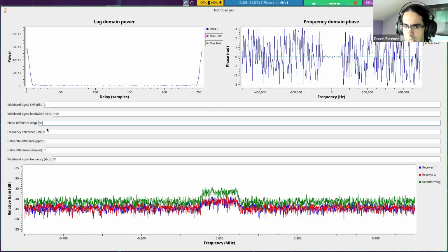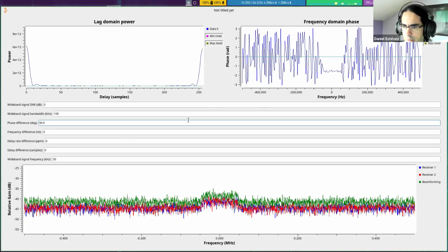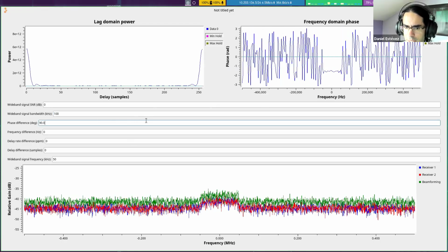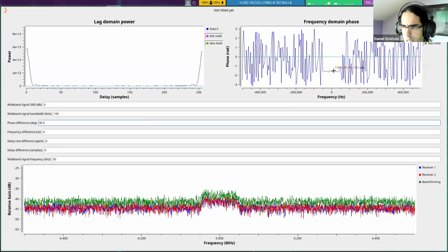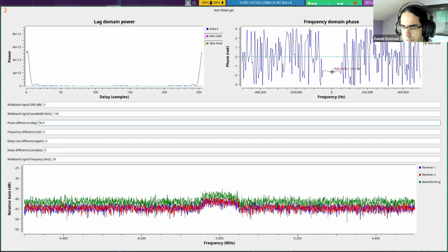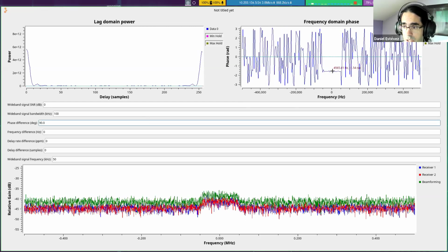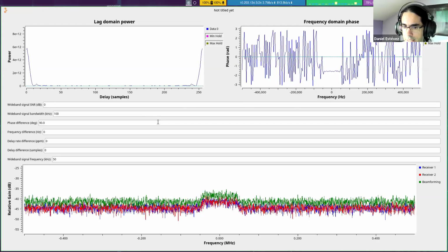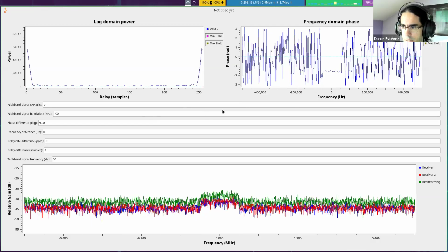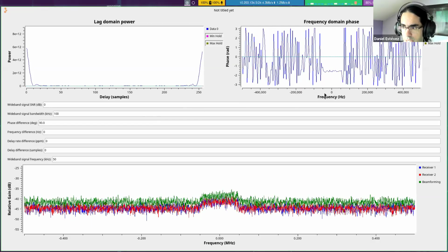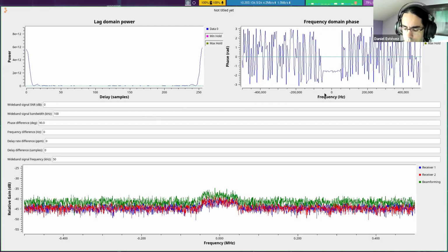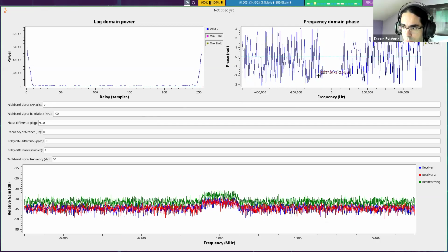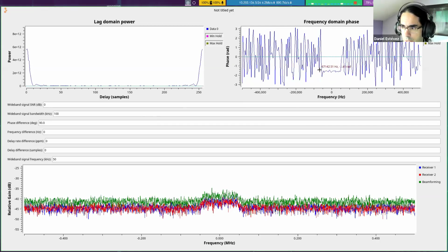Okay, how does a delay of 90 degrees look? There are all sorts of sign conventions here. Actually, we are applying the phase to the second receiver, etc. But we can see minus 90 degrees phase difference. So this is how we can measure it. If we had this for real, because, say, one of our cables adds 90 degrees more phase to the signals from one of the antennas, we could point to a source on the sky, also remove the contributions from geometric delays, and we would be left with something like this, where we can really read the value 90 degrees.